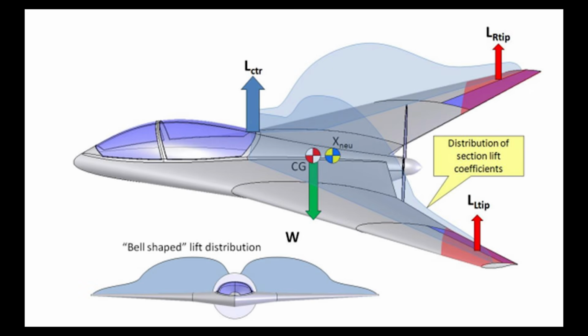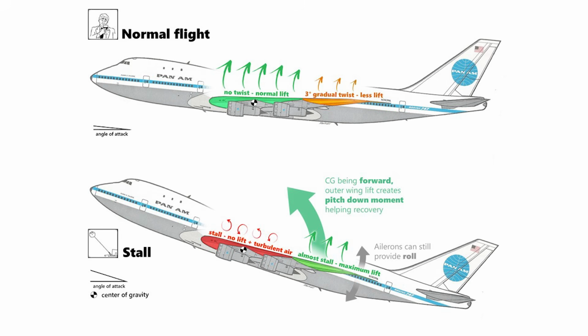With washout, as alpha increases, the lift at the wingtips becomes positive or increasingly positive. So considering a wing with just sweep, the wingtip moment arm about the pitching axis is significant for stability. If a swept wing has some washout included, the wingtips generating high lift compared to the stalling wing root will push the nose back down, just like a traditional horizontal stabilizer or tail does.